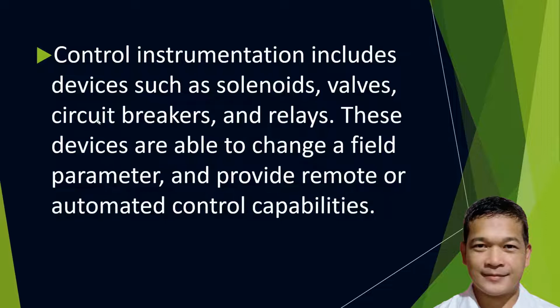Example, an electric fan. If the LM35 temperature sensor senses that the temperature is beyond the set point, which will be discussed later, then, for example, if your set point is 16 degrees Celsius or 20 degrees Celsius, once it goes beyond 20 degrees Celsius, the temperature is sent to the microcontroller.